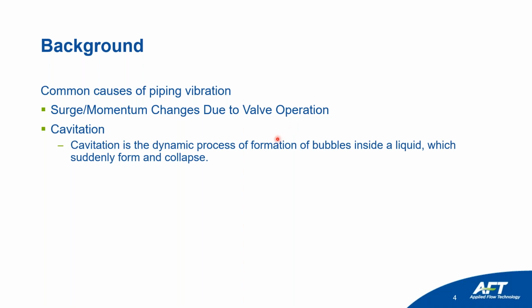Another source of vibration that can create problems is cavitation. Cavitation is a dynamic process of formation of bubbles inside a liquid, which can suddenly form and collapse, and this can originate vibrations in your pipe that also need to be addressed.